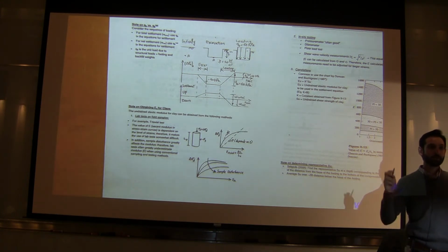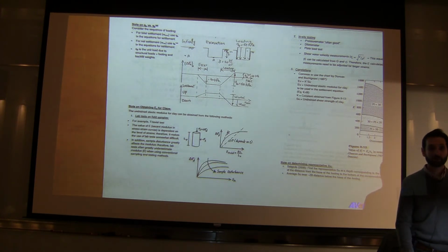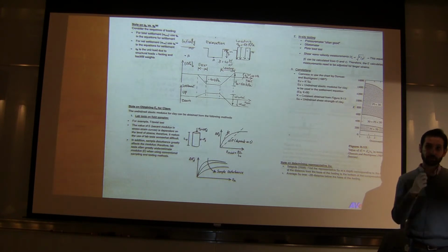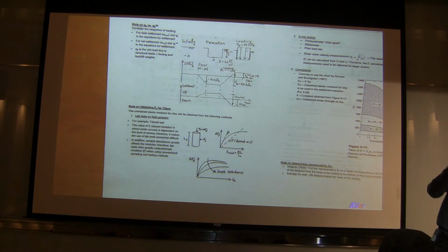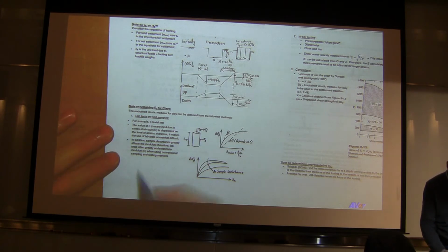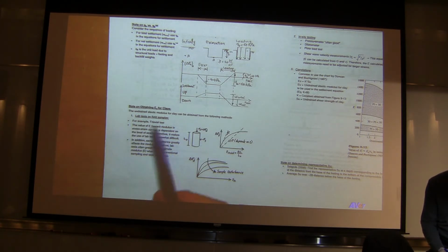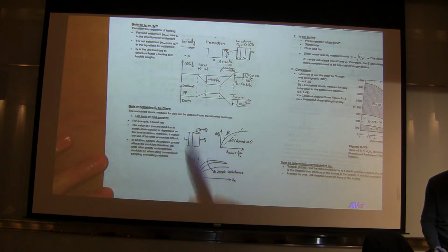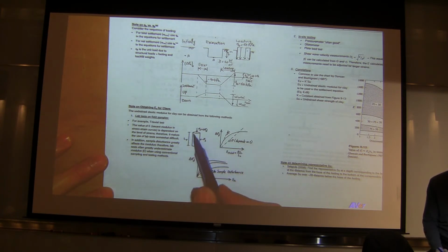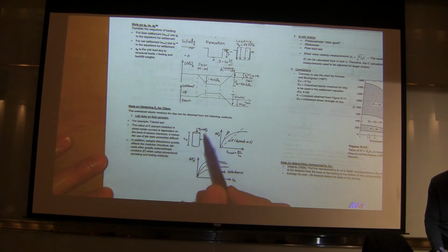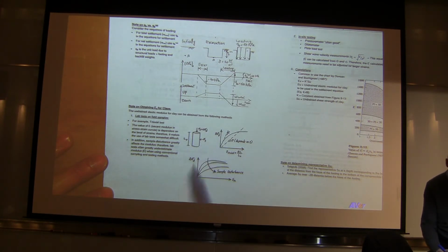Can we get relatively, quote-unquote, undisturbed samples on clay? Answer is yes. It has a high cohesion, so the particles keep it together. Once you sample it, you retain some of those in situ characteristics or field characteristics of the soil. For example, the triaxial test is one of the things that you can do. So an example is shown here. You take a sample, you subject it to sigma 3 or the chamber pressure, and on top of that you add that deviatoric load or delta sigma d.